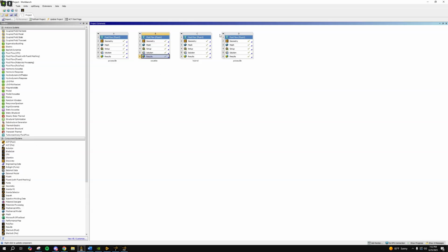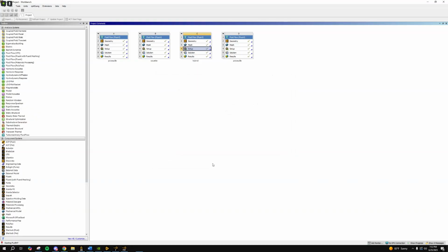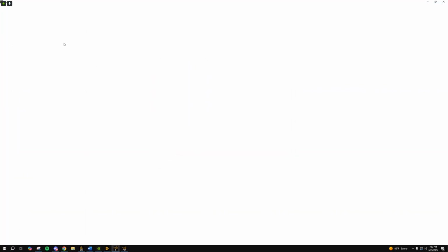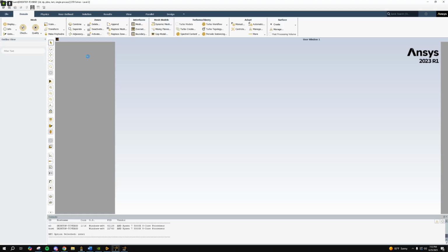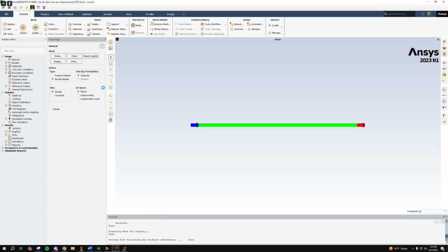So same thing as the Couette flow. I'm just going to show y'all through the setup and results, as our geometry and mesh are exactly the same as the Poisson. So we're going to head right into the setup. Make sure in here we have double precision, and go ahead and click start. Just going to wait for this to load. Takes a little bit of time. Oh, perfect. And now we can see our flow and our surface and our inlet and outlet.